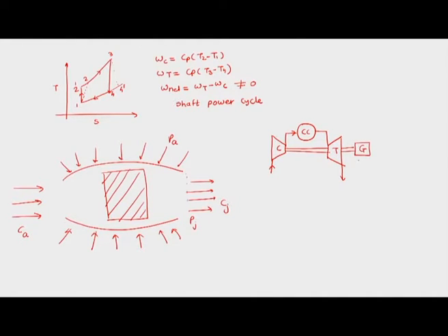So, there was W net given to the generator, and Wc was given to the compressor by the turbine, and obviously there would be some transmission losses, so on both sides it has to give more. So, the turbine has to give more work than Wc to the compressor, and the rest of the work it will obviously give to the generator.